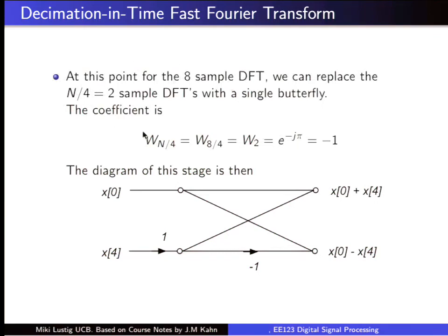What's cool about a 2-point DFT is that you've got two numbers, and you want to get the frequency domain of two numbers. How do you get frequencies out of them? It's two operations that you can do. You add them together, you get the DC. You subtract them, you get the AC, like the Nyquist frequency.